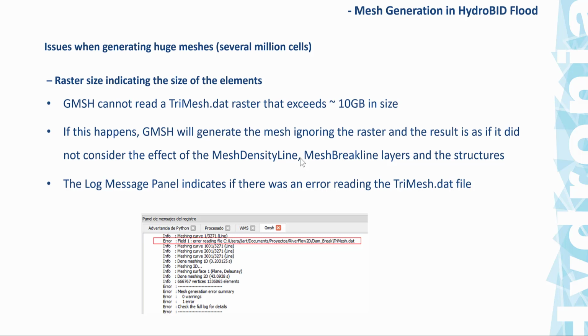It's a mesh of 12 million cells, and it works, but you have to be very careful in how you organize your data, and how you refine the mesh in order to avoid these limitations. In many projects, you are well below 1 million, and you will probably never encounter this limitation in your practical applications.